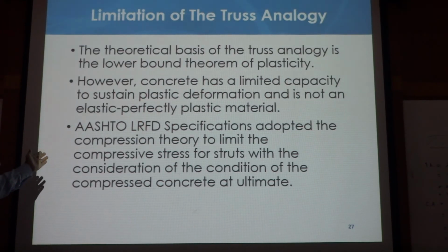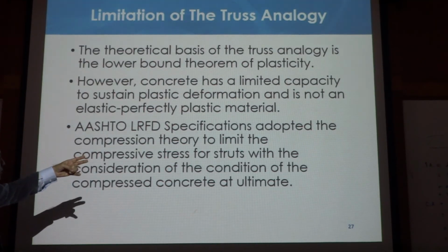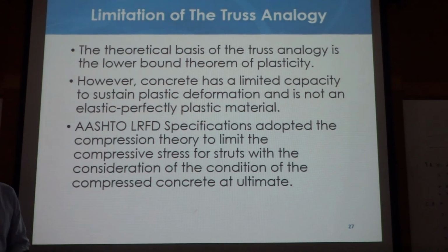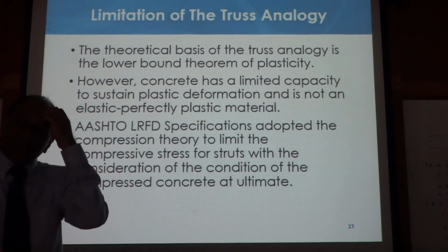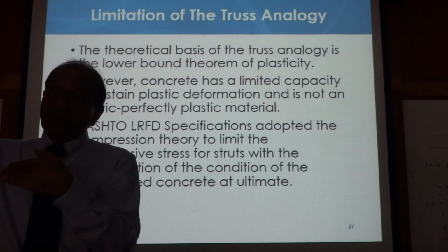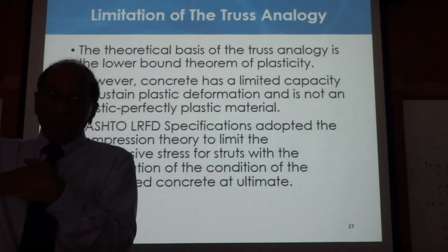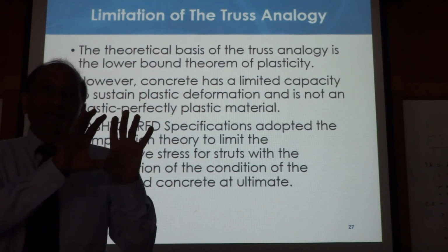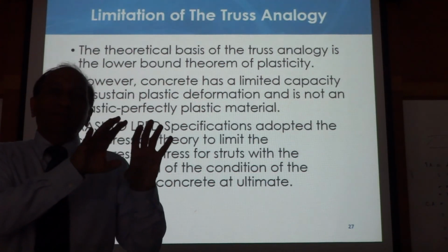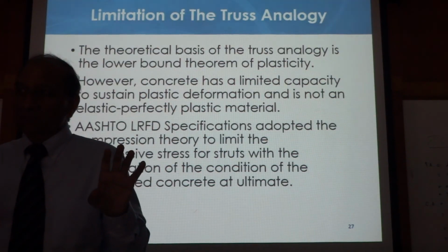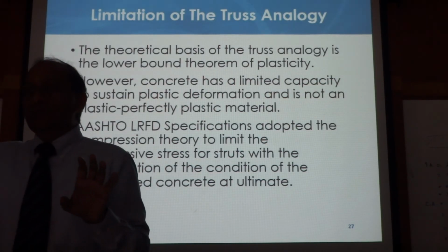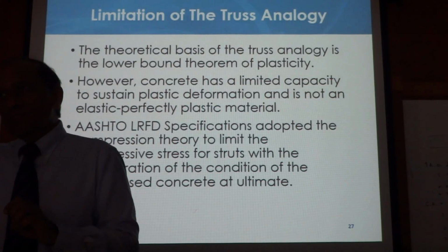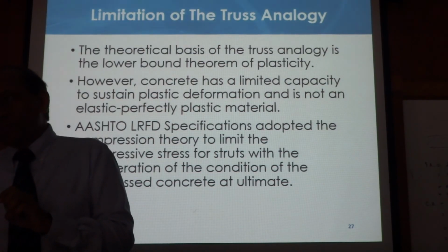It adopted the compression theory to limit the compressive stresses. So what they have done, and this is quite interesting, is that to limit the deformations and capacity of a Strut model which can have infinite capacity, they base it on the compression capacity of concrete, because the tension capacity of concrete is related to the compression capacity of concrete.